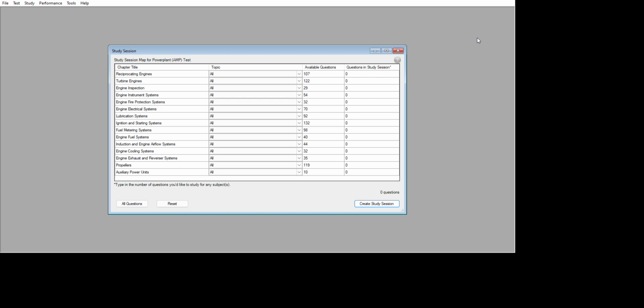What operational force tends to bend the propeller blade forward? Thrust bending force. The primary reason for careful inspection and prompt repairing of a minor surface defect, such as scratches, nicks, gouges, in an aluminum alloy propeller, is to prevent fatigue failure.